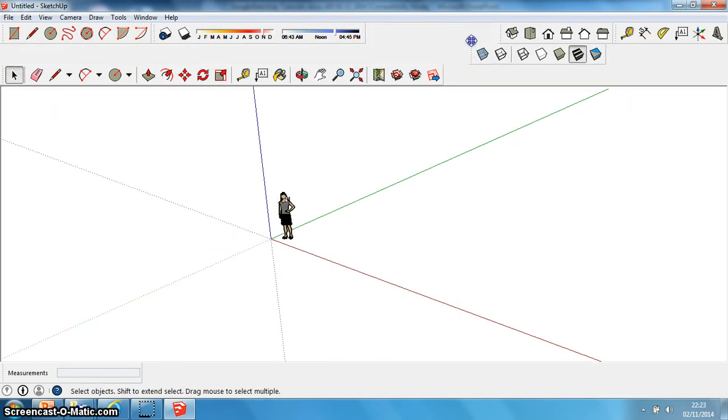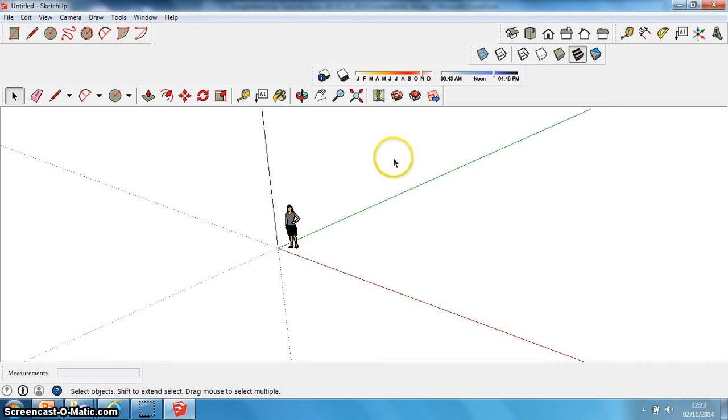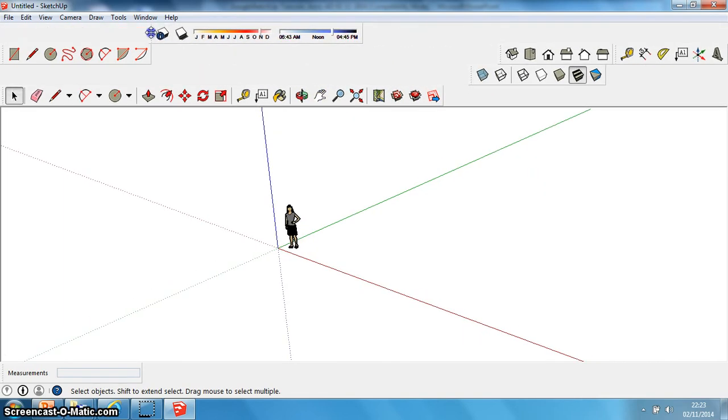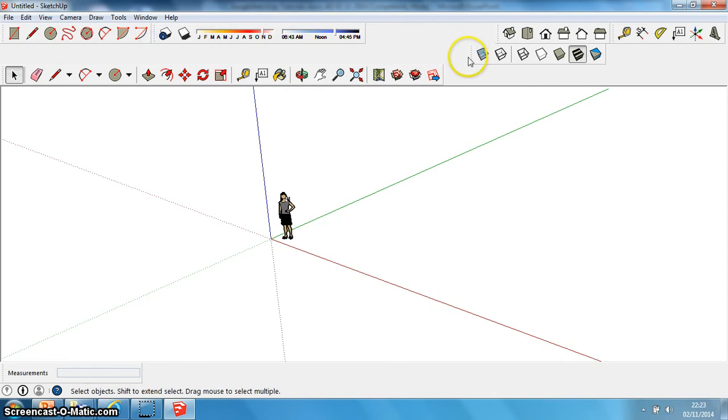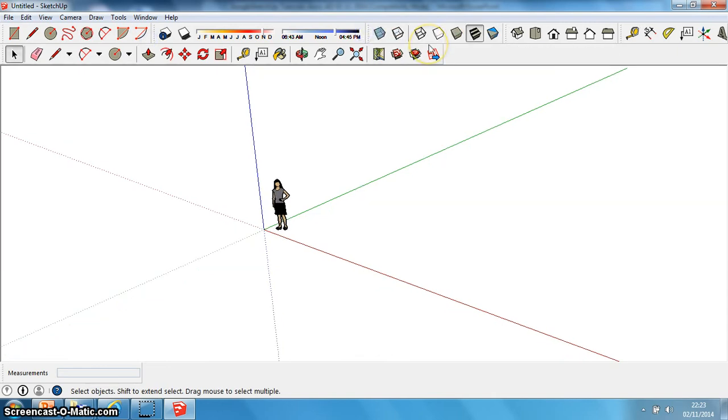Normally, SketchUp for some reason puts them all in kind of weird places, so your screen looks really messy. The way you sort that out is by clicking on the vertical dotted line on the left of each box, clicking, holding, and dragging, and that allows you to neaten up your tools a little bit. Okay, so your screen will look like this after a minute or so.